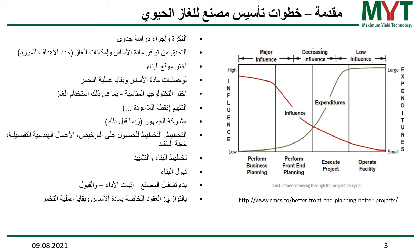Then, once you have made these early evaluations and checked these points, you need to select an appropriate anaerobic digestion technology. You've learned in the previous sections of this workshop a lot about technologies, advantages and disadvantages. And here now you have to select according to the substrates mainly what technology you would like to apply. And this includes, of course, also the type of gas utilization, CHP, upgrading, fuel provision, all these points you have to decide on.